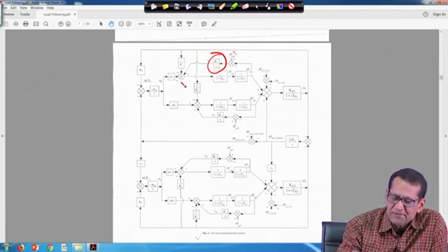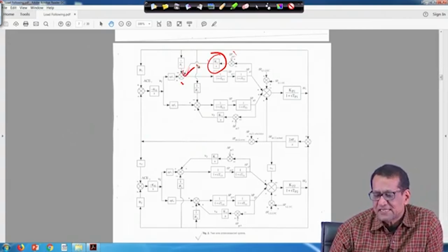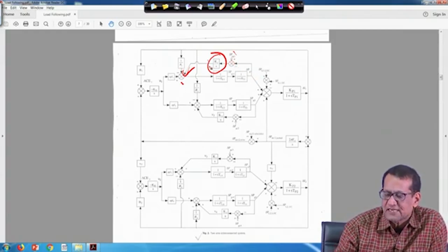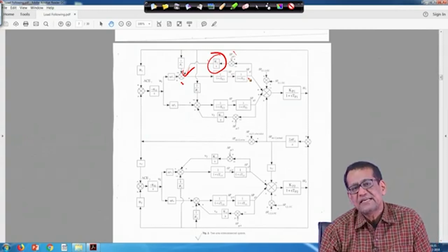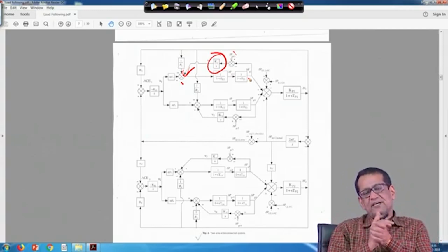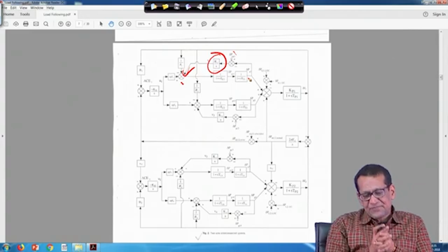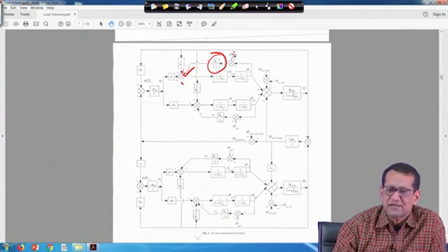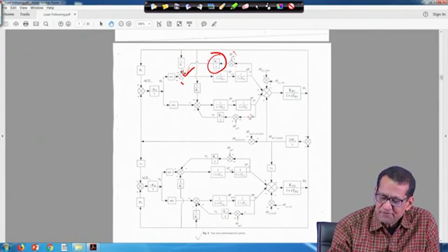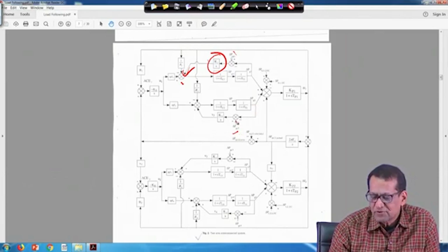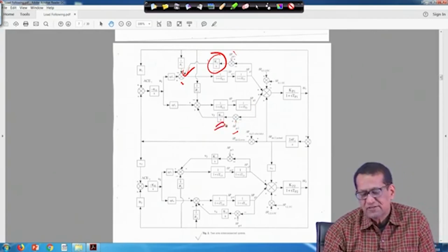Similarly, feedback is coming here, right. That means this generation, as we are taking this delta PG1 and this contracted power demand, this controller is there, so delta PG1 will chase delta PGC1, that is load following, right. So, at steady state delta PG1 will be equal to delta PGC1; it will chase the contracted power demand. Similarly, for unit 2 you have delta PGC2 and delta PG2, and this is integral controller K2 upon S.